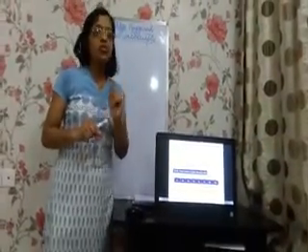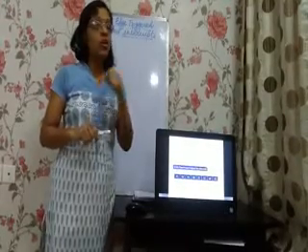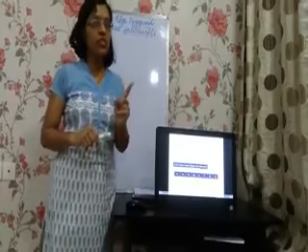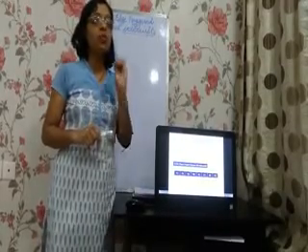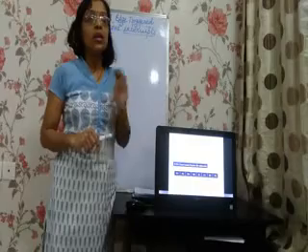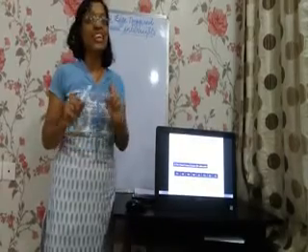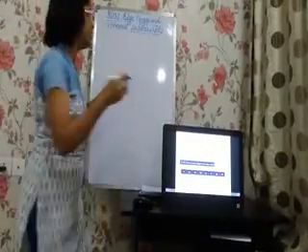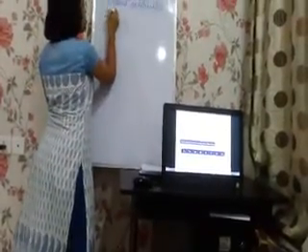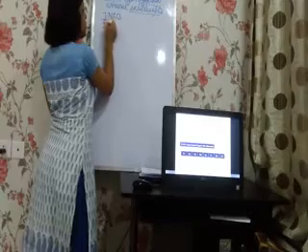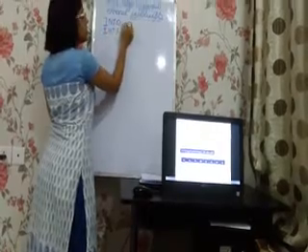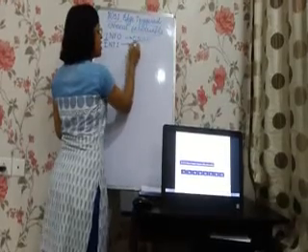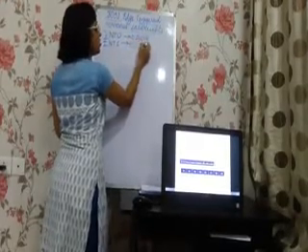We also saw how to program timer interrupts. We discussed the IVT yesterday. Then we saw how to program the timer interrupts, and we also took the external interrupts. Yesterday I told you that there are two external interrupts, INT0 and INT1. The vector addresses of the ISR for these interrupts are 0003H and 0013H respectively.